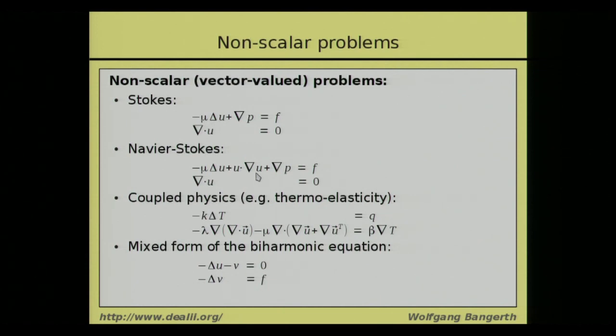Then, of course, you have coupled problems like thermoelasticity. Let's say you have a temperature variable, and the temperature diffuses in a medium. There is a heat source Q, for example. The temperature diffuses, and then coupled to this you have an elasticity equation where the source term for the elasticity is the gradient of the temperature.